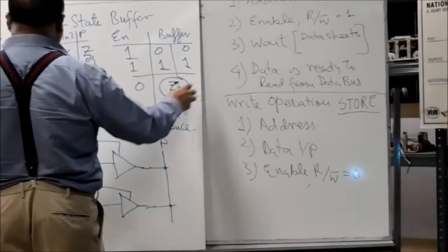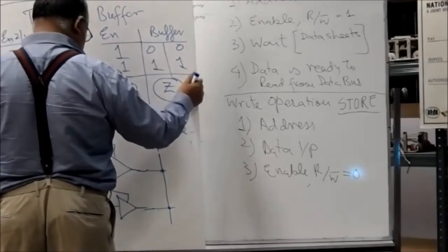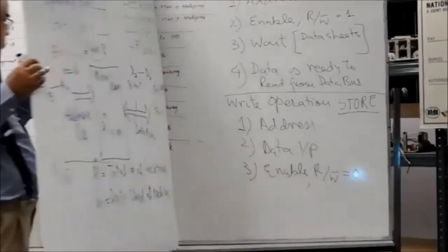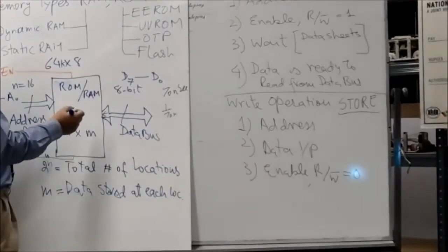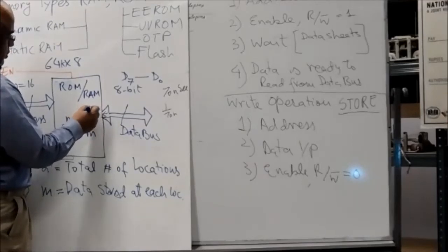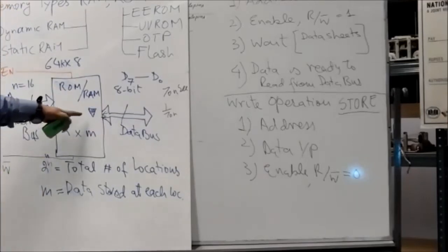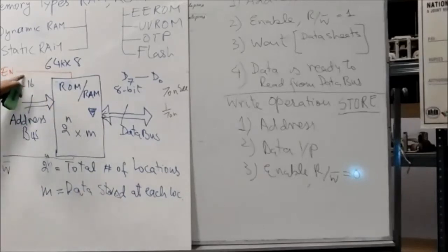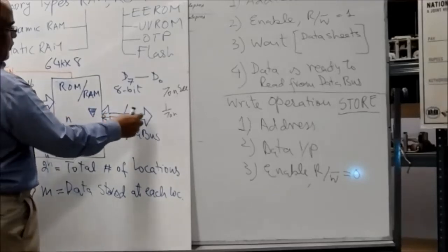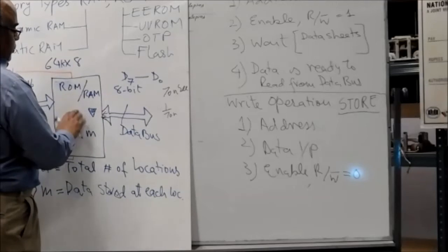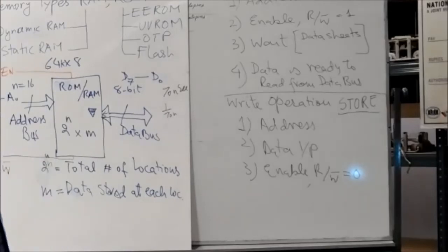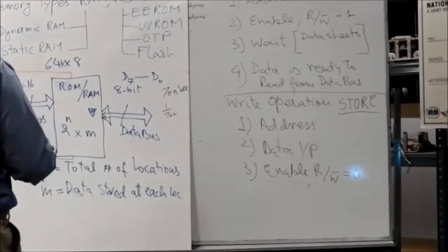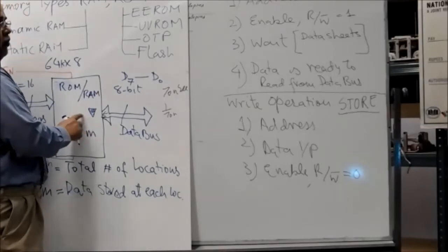So coming back to the memory IC here, this is shown as a symbol over here. This symbol means that when enable is 0, data bus is floating. It's like this IC is not present in the circuit. As if you took the whole IC out and kept it outside. It's not present in the circuit. So this is a very powerful combination.